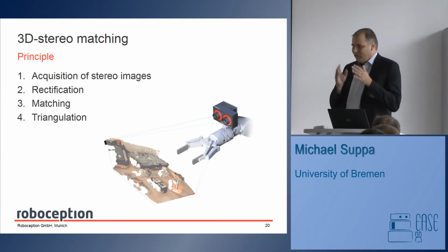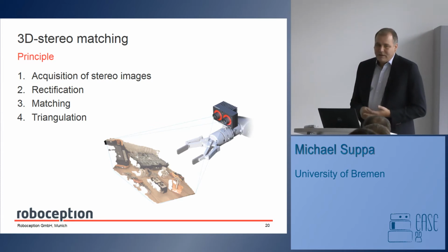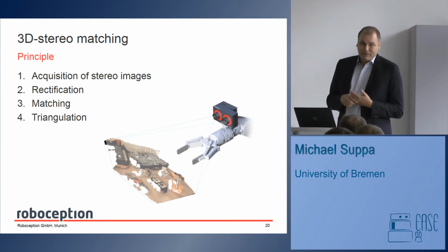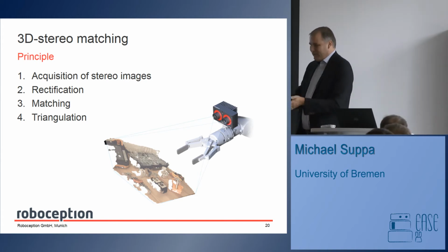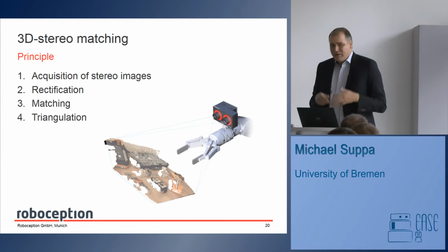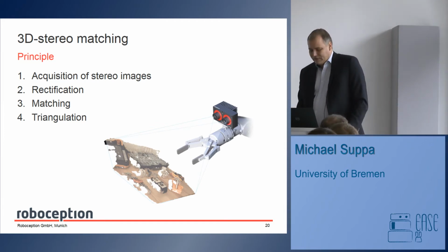You need to do the matching and map the steps, and that requires algorithms that a couple of years ago it was not possible to compute. The same thing that applied to CNNs, where you now have computing resources, is also good for stereo, because now you can have nice algorithms that can be computed on board, and then you can get your depth image.